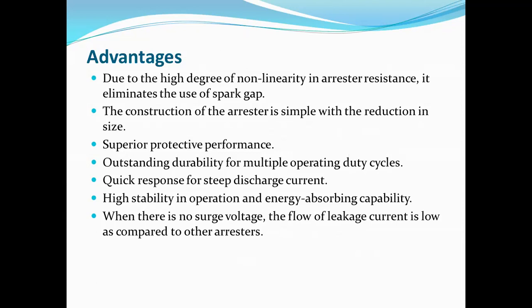Means actually we are using the gaps between these two rods. So instead of that, what we are doing, we are using the zinc metal, right? Zinc is having non-linear characteristics. So due to that, instead of using those gaps as a resistance, we can use that zinc only for producing the resistance, means for producing the open circuit or maximum resistance under normal working conditions.